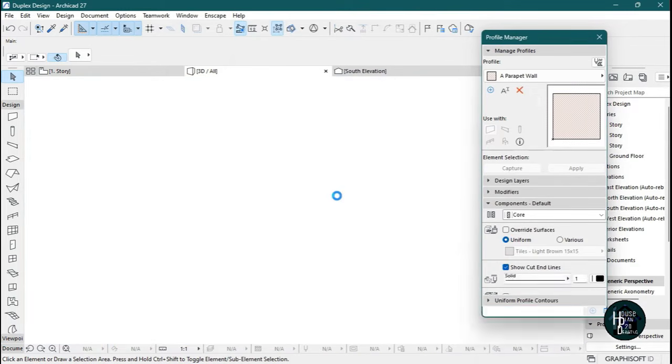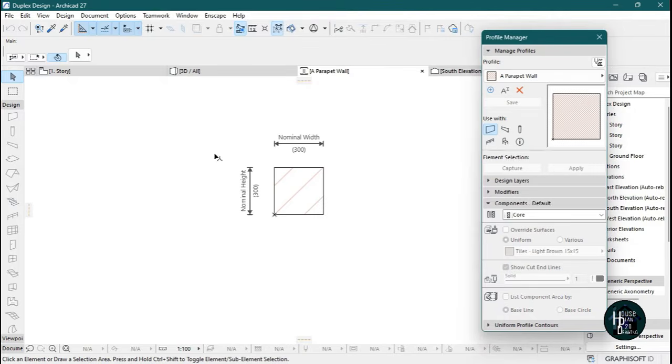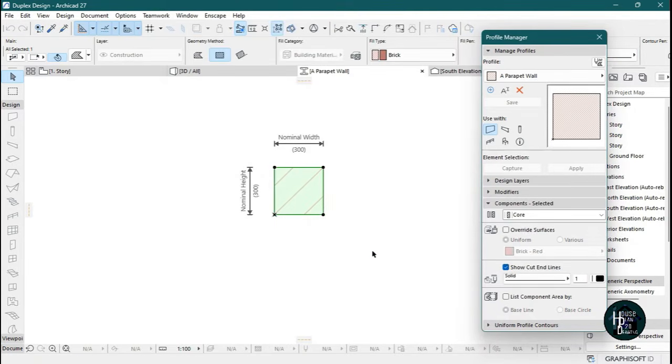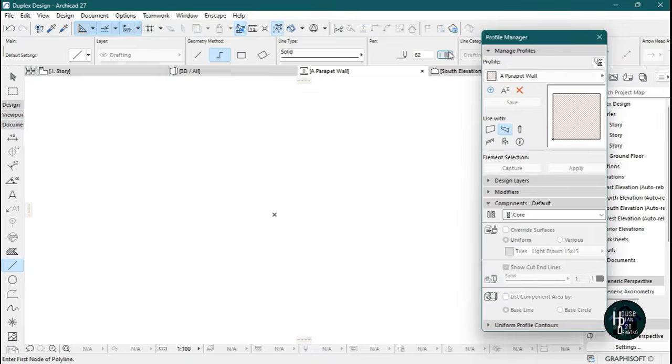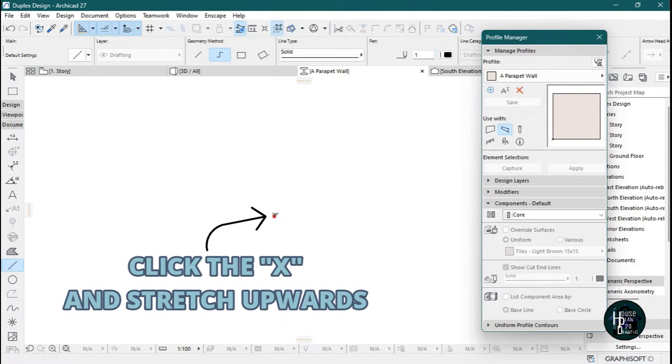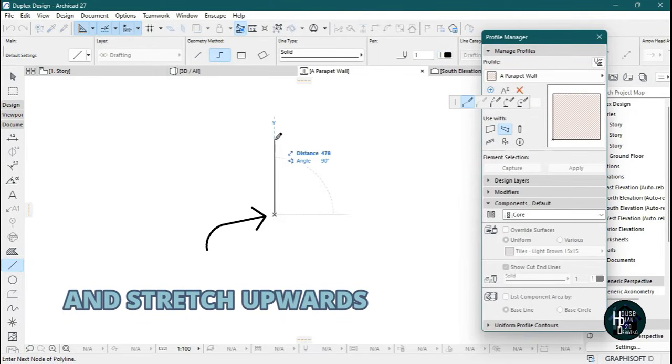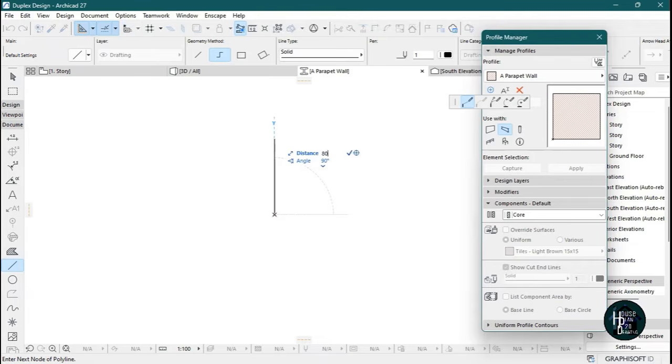All right, so I'm going to load up, and just align this and delete it. You don't need it. Okay, come here and select this beam, untick this wall, come to the document section here, click on the line tool, and let's try and sketch the parapet wall. So I'm just going to give it a distance of, let me say, 800. Okay, click enter, move it to this side here, click 225. All right, bring it down, click and double click this side.